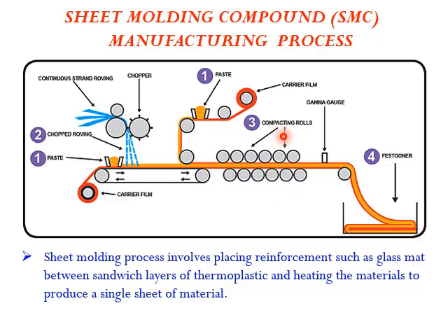The distance between these two rollers is going to control the thickness of the sheet which you are going to get, so according to that, the distance between the rollers is set. Once that is done, we are going to have a gauge, which is going to control the thickness of the sheet, and then we are going to get a final product. Once this final product is done, you can have a continuous one also, or you can chop it according to the required length.